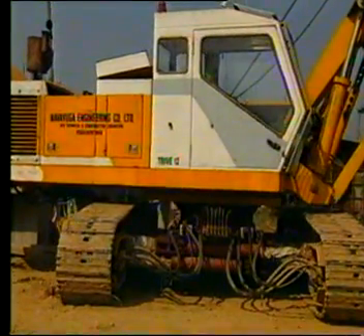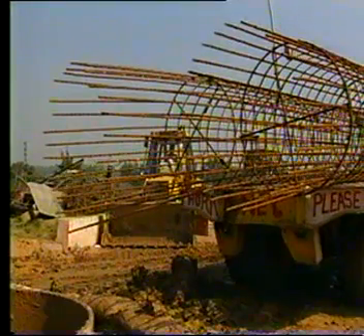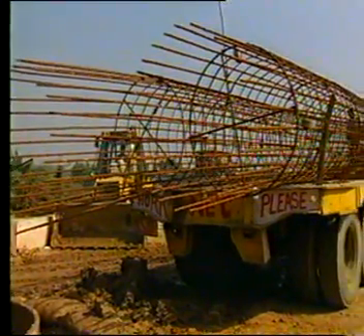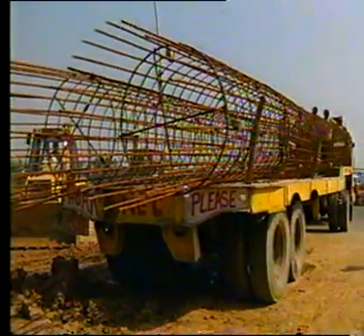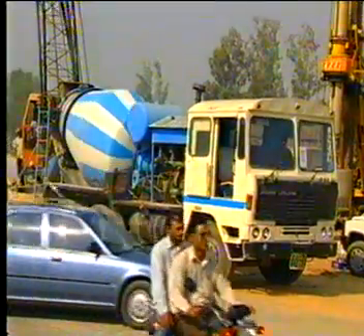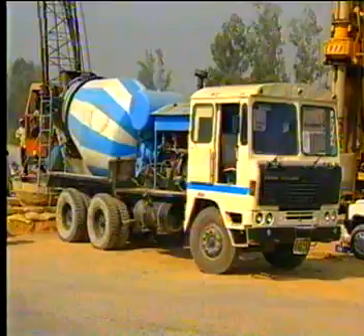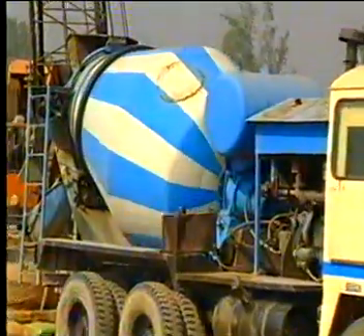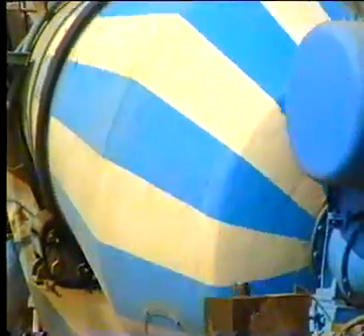equipped with controls. The reinforcement cage for the cast in situ pile is fabricated in the fabrication premises and brought to site on trailers. The concrete, which is to be used for casting, is made in the mix plant under strict quality control and brought to the site in transit mixers.